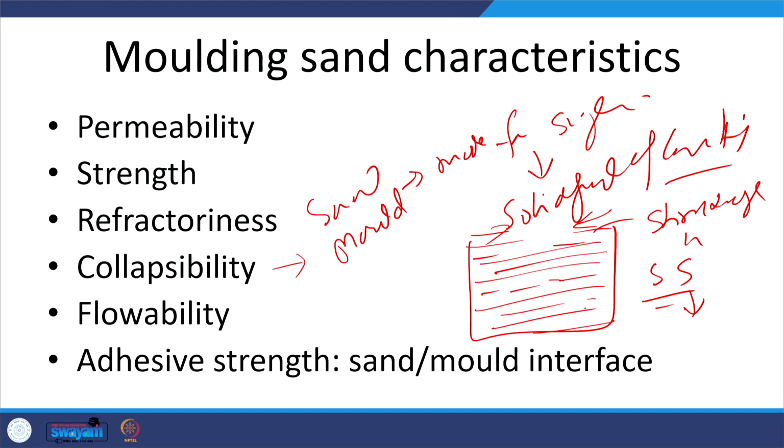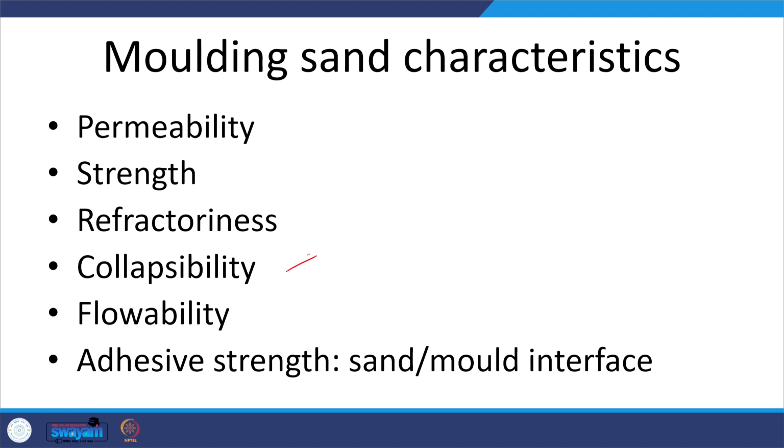If it does not, then it will tend to develop residual tensile stresses, which will promote the hot tearing or cracking tendency or distortion tendency. Okay. So, it is important that during the solidification, when the cooling of the casting is taking place, the sand mold should break easily.